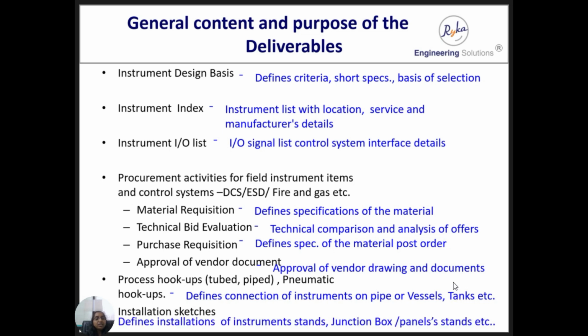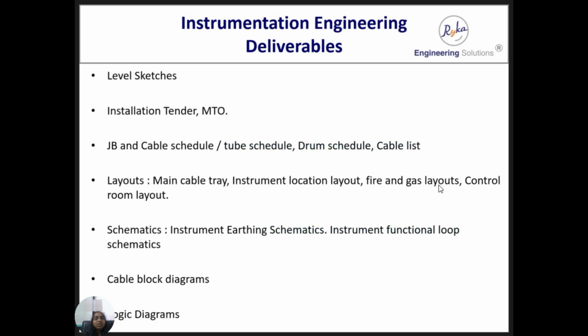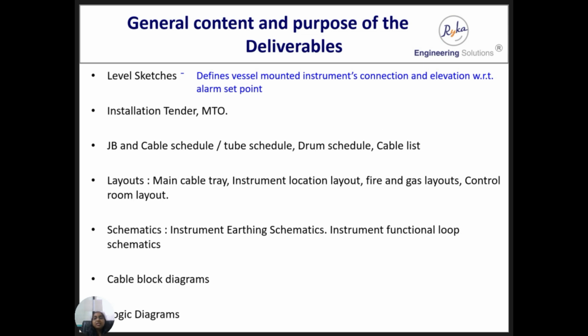Installation sketches define installations of instruments, stands, junction boxes, panel stands, etc. So these are the next set of deliverables. Content and purpose of the deliverables we'll see here. Level sketches define vessel mounted instrument connections and elevations with respect to alarm set points.